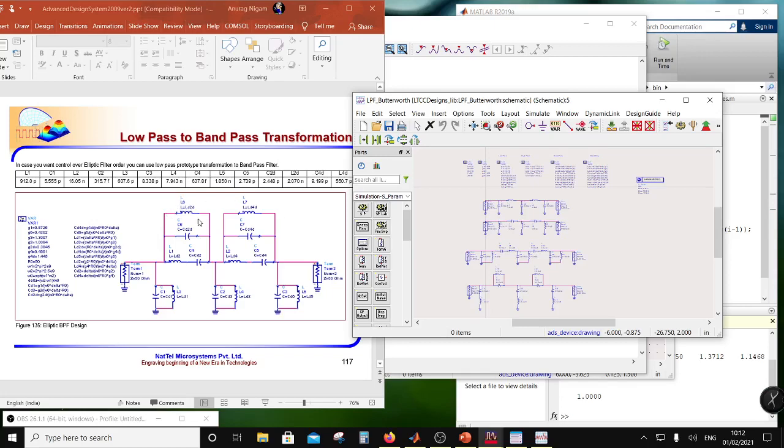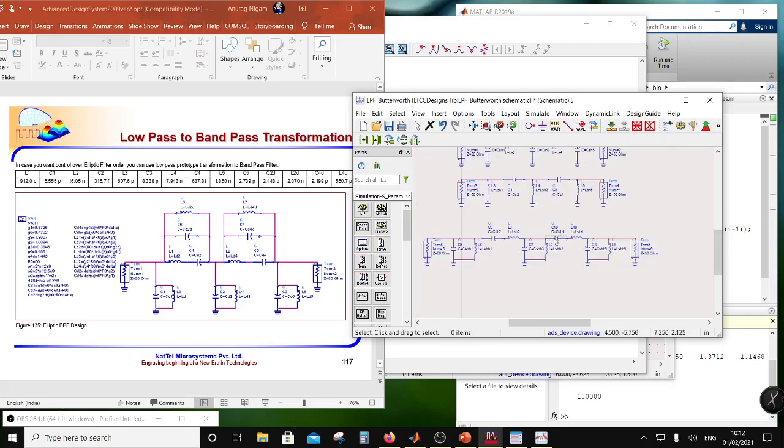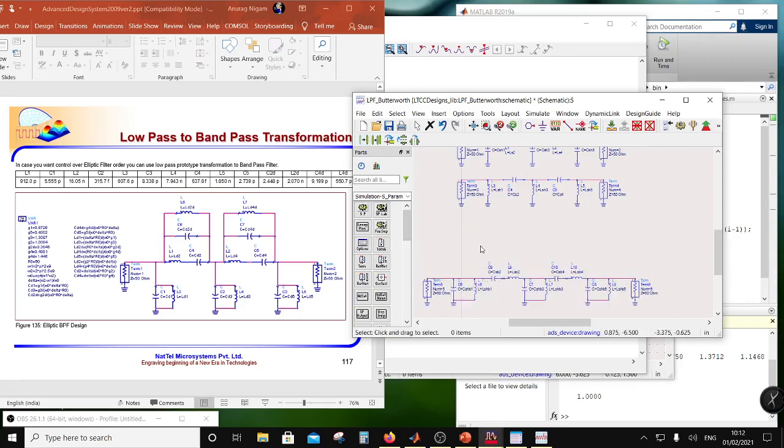What's going to happen is that this element which you see here in series will come in shunt, and what you see as a shunt will go in series, so it will become a band stop filter. But that transformation I'm going to leave to you. I'm just going to show you up to a bandpass filter. All these are correct. The only thing I need is 2 more elements on top of it, and this would be your bandpass filter.